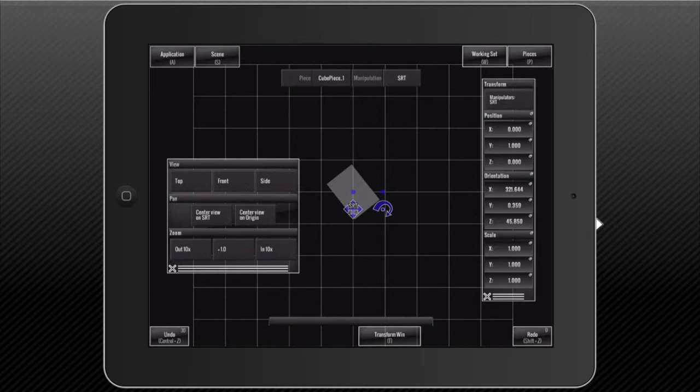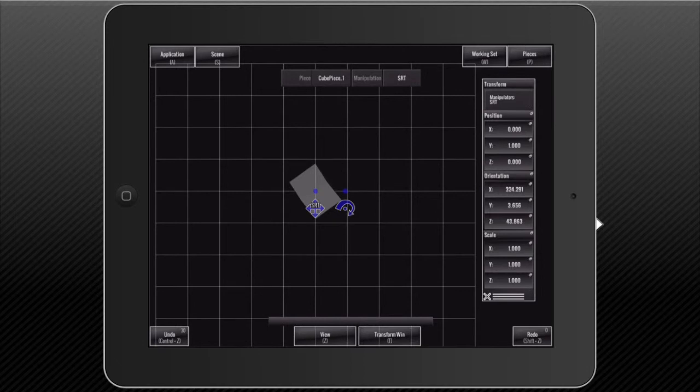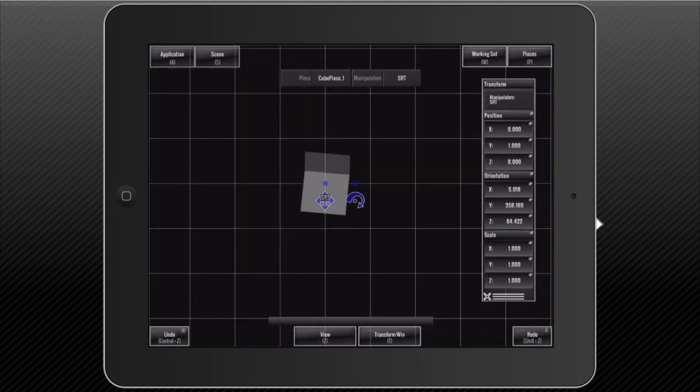The orientation values below are for rotation. And so it rotates the object around the given axis, and you can drag it. These are done in local space to get around a weird mathematical thing called a gimbal lock, which NASA had some problem with a number of years ago, which makes it very intuitive in that it's always going to be rotating on an axis of the box. But the unintuitive part is that sometimes when you rotate on one of these axes, all 3 numbers will change, which is technically accurate for a gimbal locked object, or for coming up with gimbaled numbers for a local rotation.